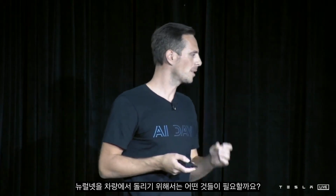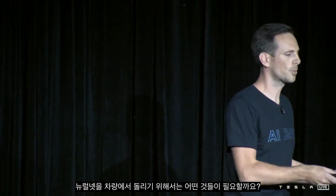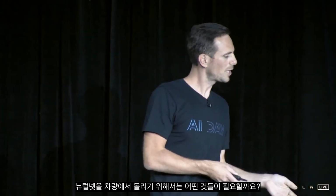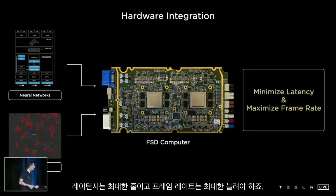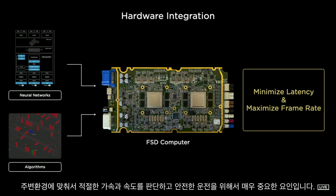I'd like to give you some idea of what it takes to take our neural networks and move them in the car. The two main constraints that we're working under here are mostly latency and frame rate, which are very important for safety, but also to get proper estimates of acceleration and velocity of our surroundings.